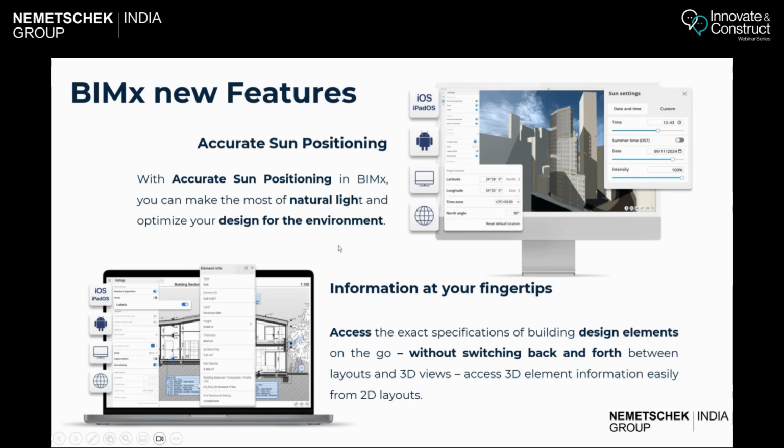So BIMx talks directly with Archicad and gets all the sun positioning from the authoring tool, through which I can run different simulations by adjusting the intensity and the time zone of that particular site. So with this, I can make decisions on where to place my glazing and where to place my openings. So these kinds of simulations can also be run with BIMx.